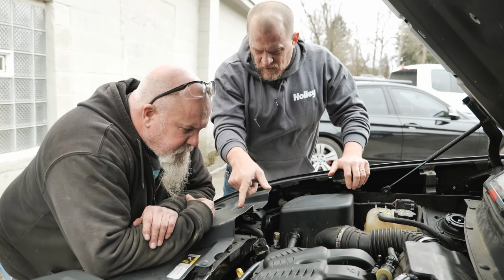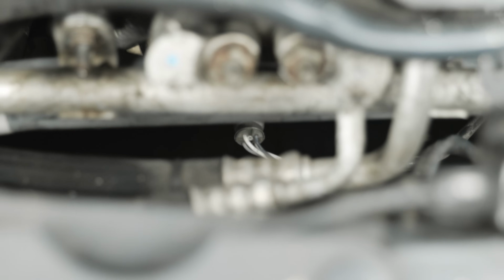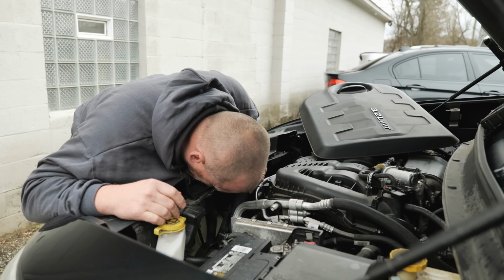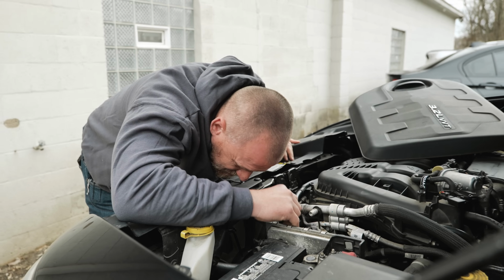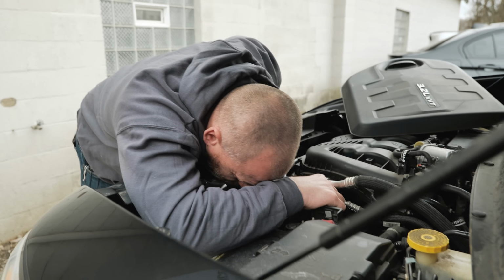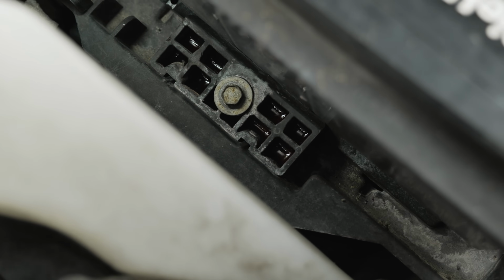This is bank 2. All right, I want to look at that oxygen sensor. I'm just trying to do some visual inspections on this O2. There's nothing I'm going to be able to show you guys, not real easily. I don't see anything, nothing obvious as far as visual. I smell coolant. Look at this, in the battery hold down, that's antifreeze.